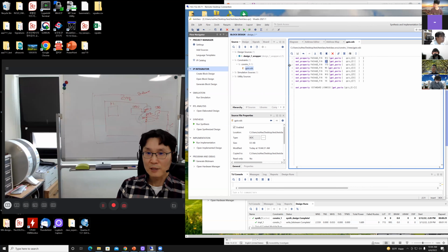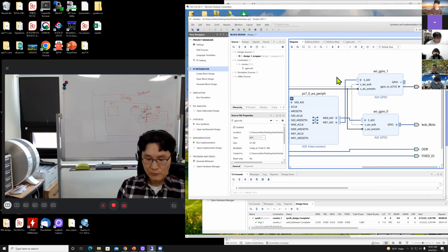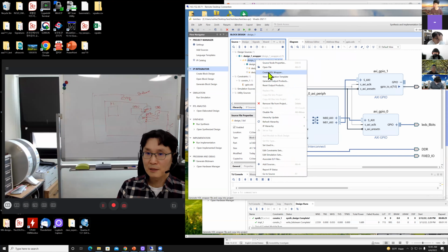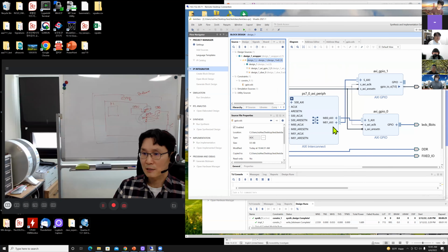That's it actually. That's what you have to do in hardware design. So we did everything. Then to synthesize and place and route, before you do that, you have to generate the top HDL file. That is standard procedure in Xilinx.